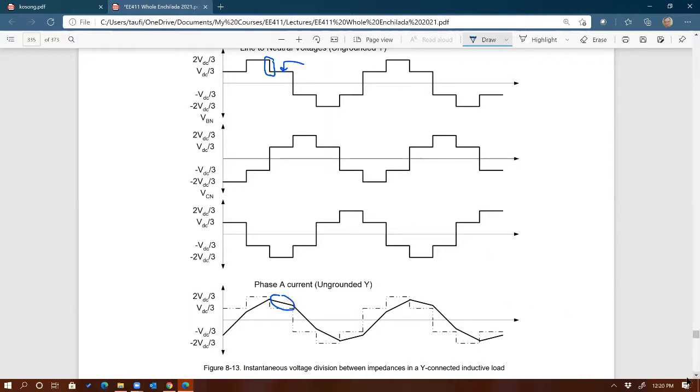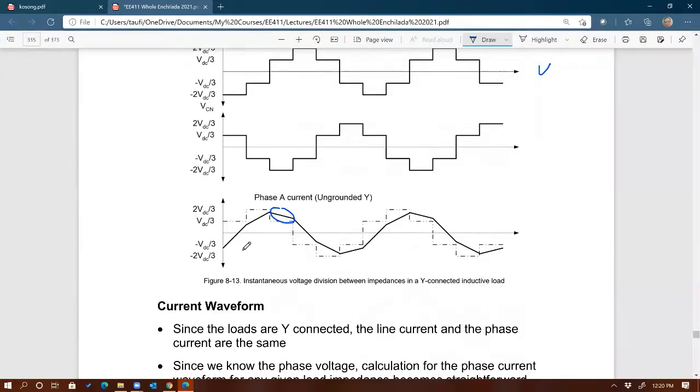In this sense, it's actually better because you can see the quality of the output current is actually more sine wave-like than the voltage. So that's what you get. That's the gain that you get from having an inductive load: the benefit shows up in the current, not in the voltage. Voltage stays the same, but current now has better quality, right? Okay. Now, in the next